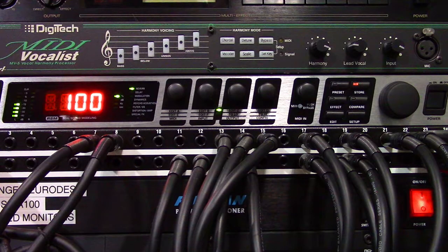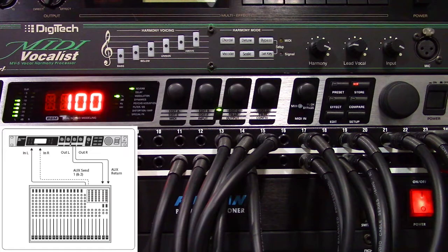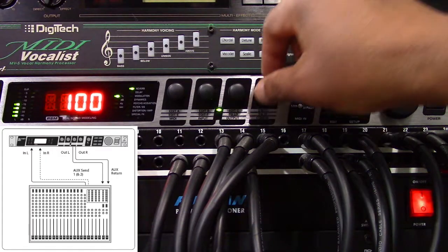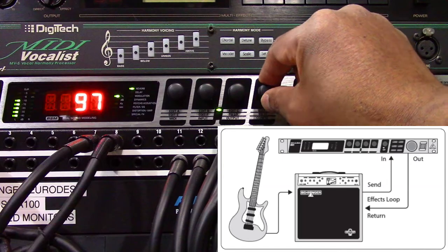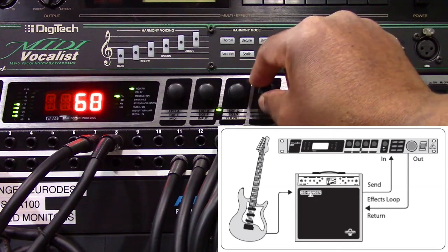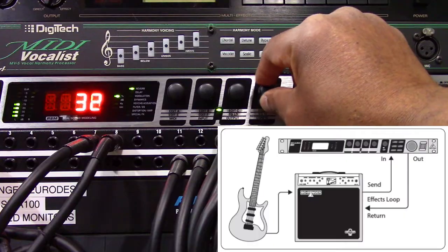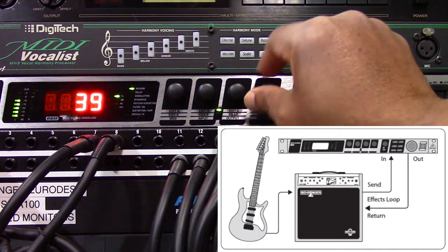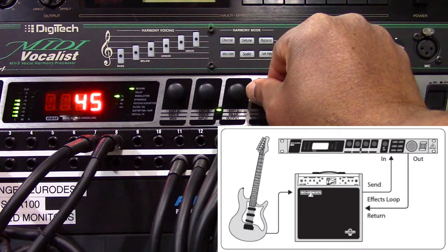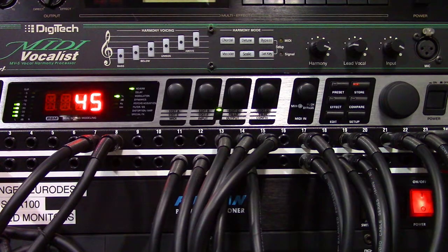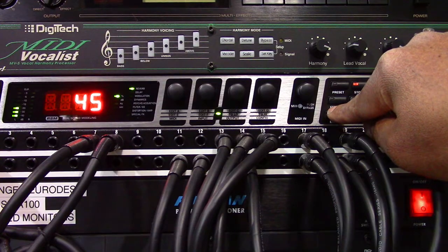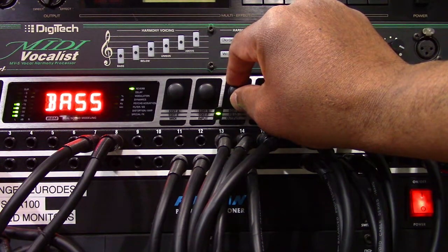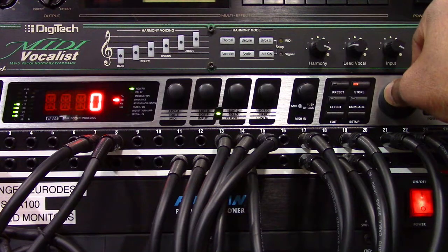Now here's some other points of note. If you use the FX2000 in the aux bus with your mixing console, set its value to 100%. If you're using the FX2000 with a guitar amplifier in a series effects loop, set it between 20% and 50% depending upon your amplifier type. So you're going to have to play with this to get it right. For the effects of parametric and graphic EQ, the mix bypass control allows you to manage the gain. This is important, so keep that in mind.